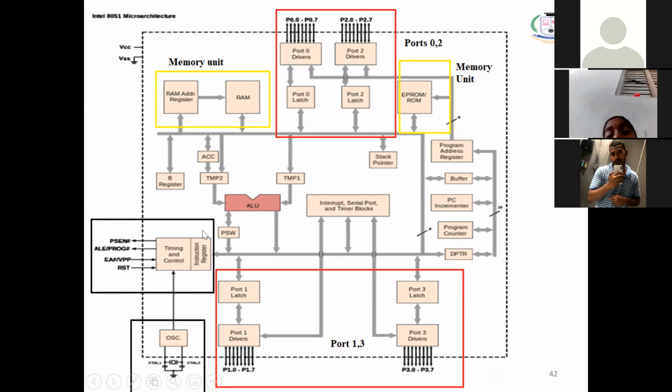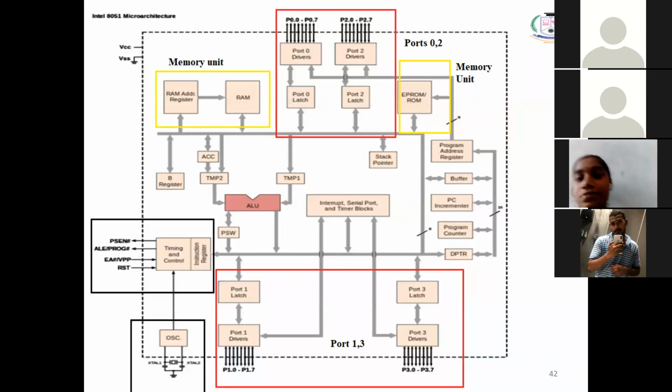This is over. Now you come to the heart of the system. The heart is nothing but the ALU part, the arithmetic and logical unit. See, this is my ALU. In the ALU, for all processors and controllers, which is the primary register? Accumulator. The accumulator is the primary register for all processors. So here also the accumulator. What is the length of the accumulator? Anyone? Sandhya? 8-bit. Very good. Because your data bus is 8-bit, your accumulator's length is also 8-bit. There is no deviation on that.